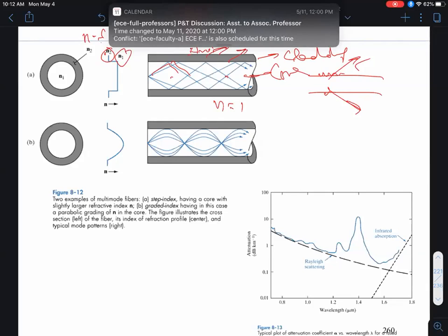And for the cladding, you can have a sharp change as shown over here, or actually a better design is a gradual modulation of the refractive index, okay? And you can do that by putting impurities into the glass, which change the refractive index in a nice smooth fashion. If you do that, you have a graded optical fiber. And the nice thing is that you get constant refocusing, kind of like in a lens, okay? And that causes less scattering.